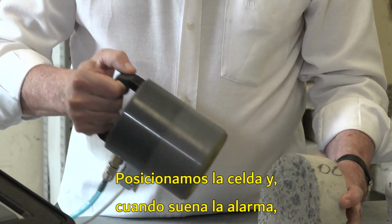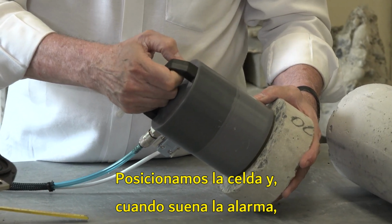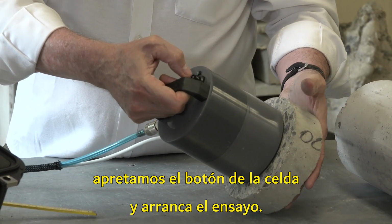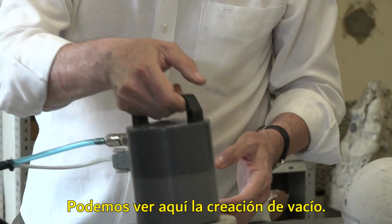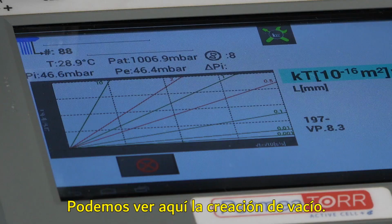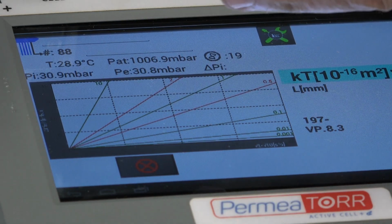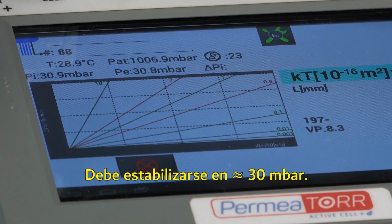Now we have to place the cell when the alarm sounds, and then we press the button and the test is started. So you see that we have vacuum here. The atmospheric pressure is about 1007 millibars, and the pressure of the two chambers is shown, which is around 30 millibars. It has to stabilize around 30 millibars.